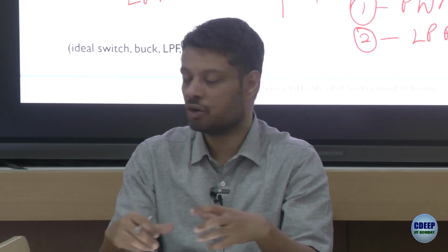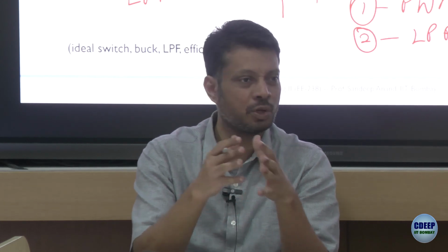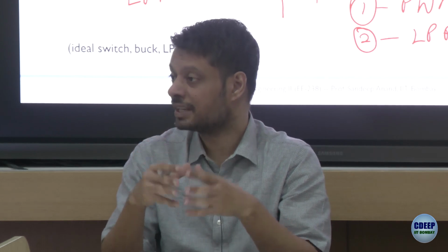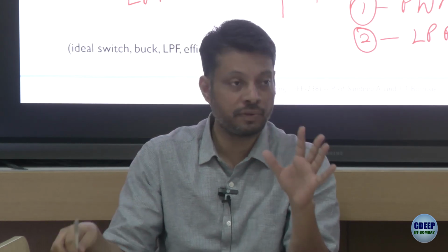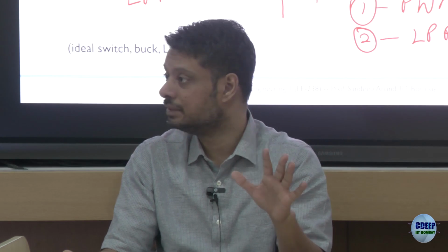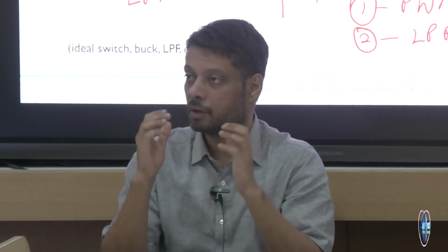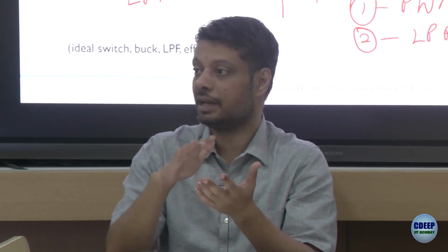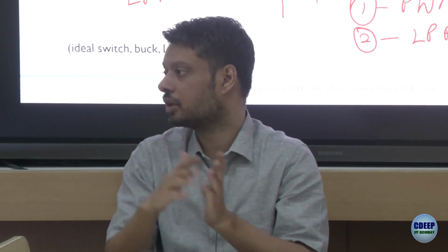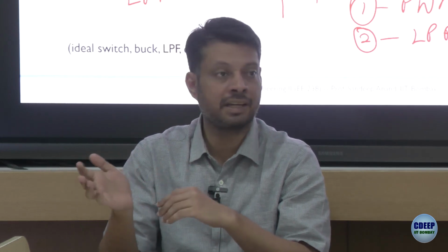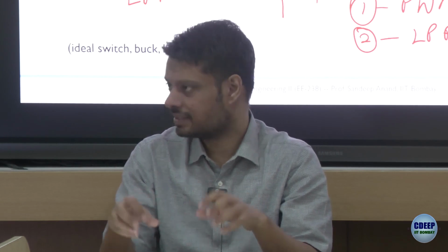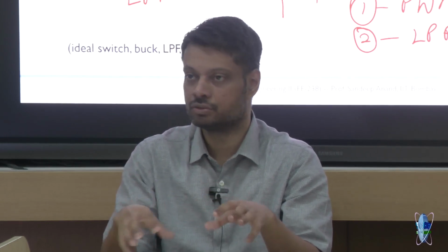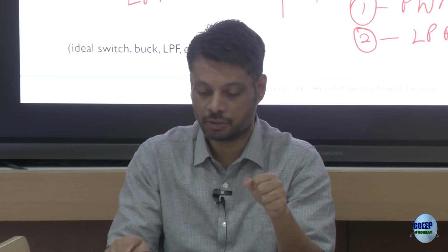This is how most of the power electronic converters operate, right? We don't want linear regulators. We don't want to create a lot of losses. The objective is that you have a low frequency, the 50 hertz or a DC voltage. You overlap it with a very high frequency component, and then you filter it out. In the process, you change the voltage levels or the magnitude or the frequency, whatever you want to do. That's the basic principle. As we move forward, I'll give you more examples, so this concept becomes more clear to you.